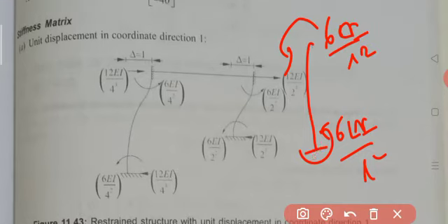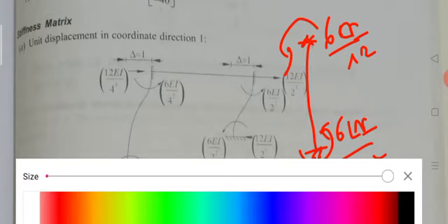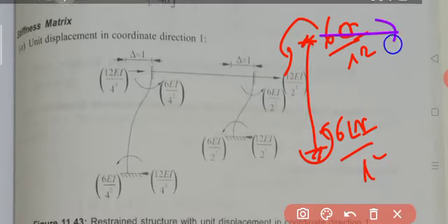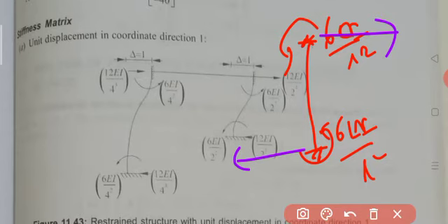Fixed end. Then you should determine the reactions at both the ends. In this case there is no external force. The net end moment creates an anti-clockwise moment on this structure, so the reaction should be developed in a clockwise direction to resist this moment. Our horizontal reactions may be developed in this way: one reaction and another reaction create a clockwise moment, while the net end moment is anti-clockwise.